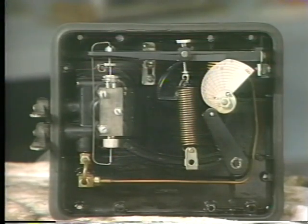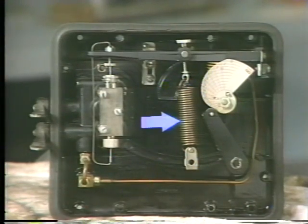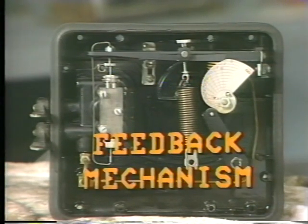All of these parts, the drive arm and gears, the cam, cam follower, spring beam assembly, and spring, make up the balancing mechanism of this positioner. Sometimes it is also referred to as the feedback mechanism, because information about the position of the actuator is fed back through these parts to ensure that the actuator is positioned where it is intended to be.